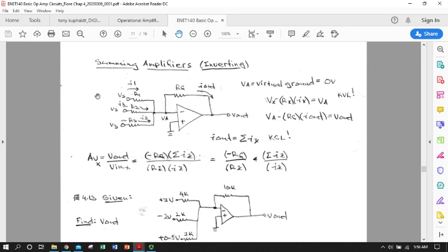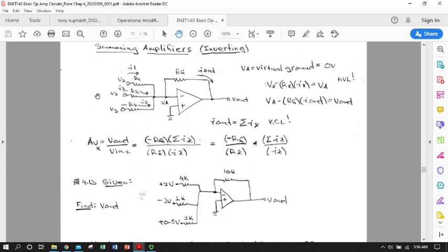When we left off, we had finished the basic concepts of idealized op-amps with negative feedback. Just to recap, that is infinite input impedance into both the inverting and non-inverting terminals. And second, and probably more useful, is equal potential at both of those terminals. So that's what allowed us, in the case of the grounded non-inverting terminal with an inverting amplifier, to have that virtual ground at the inverting amplifier input. And that made it very easy to simplify circuits and calculate gain.